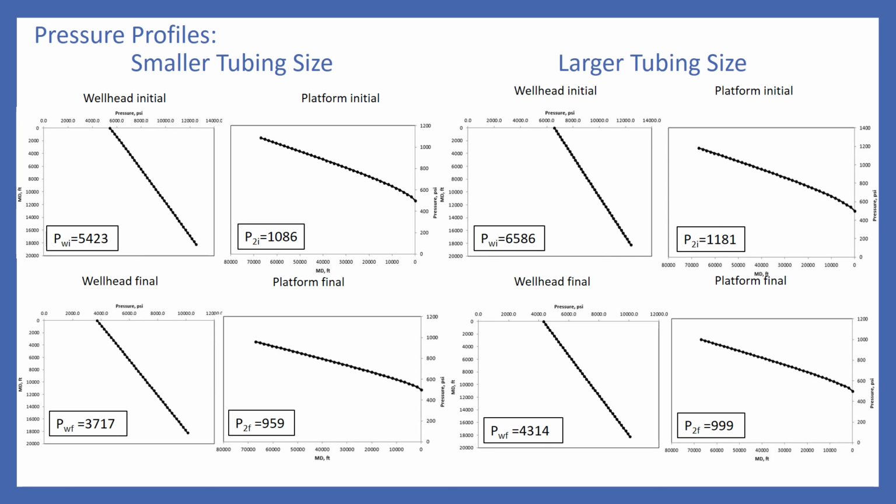Decreasing the tubing size did cause a noticeable change in pressure profile. The smaller tubing size led to a much higher wellhead pressure than the base case, confirming our notion that we believe the smaller size is choking the well. The final pressure profile of the smaller tubing was the closest that we observed our reservoir of getting to subcritical flow. However, the larger and smaller tubing sizes were still able to stay in critical flow to preserve the validity of our Excel program.